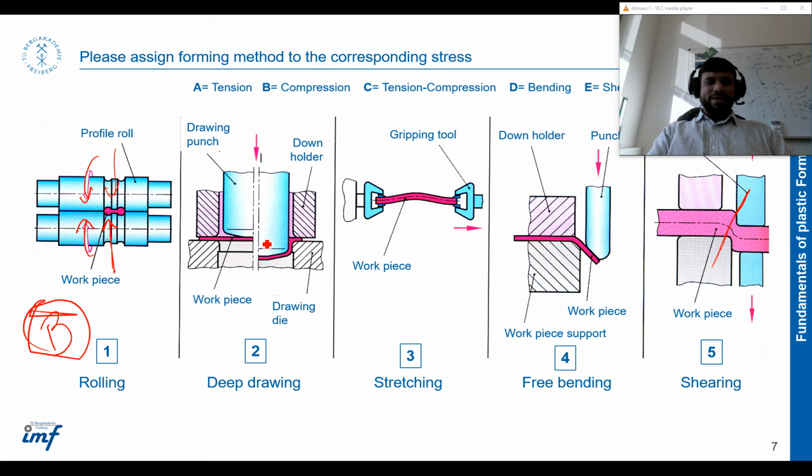If I look at this area here, of course there is bending going on. But generally, we consider a sheet a 3D block, because usually it is not 2D. Within this thickness, the sheet is undergoing compression along the axis, and along this wall, the sheet is undergoing tension.